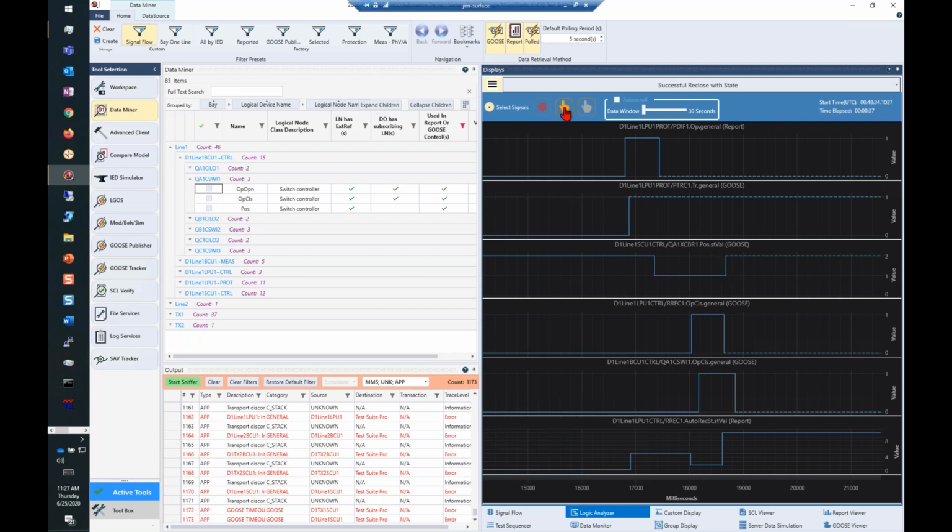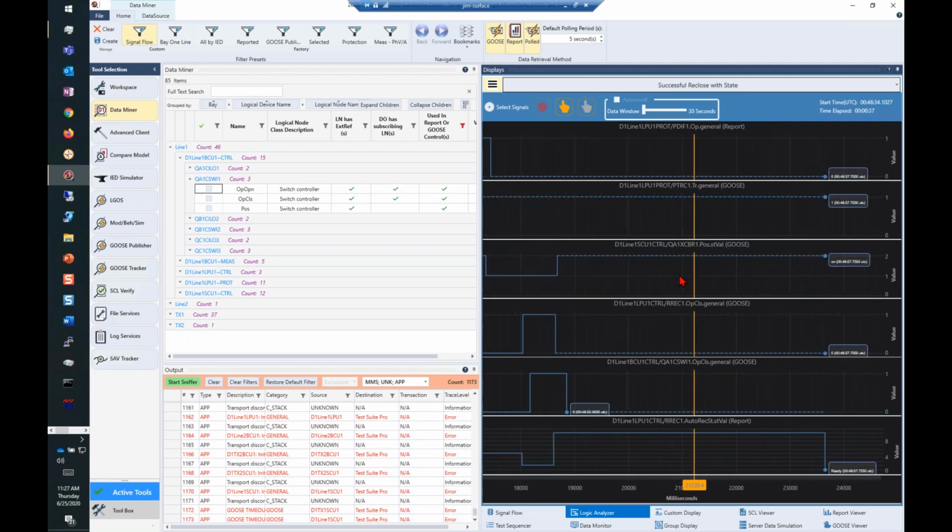And we've got these cursors on here that will show you the value of the data item where they are. So like right here, on the auto recloser status, you see the value shown right here. It went into trip protection, and then if we keep sliding over, you'll see the different states that it progressed through, in progress, and then over here, you should see it go back to ready back here. And what this is doing, it's finding the nearest event and highlighting the value at that event that we received.